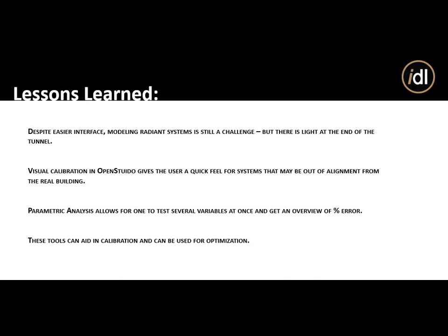And so what we've done before is actually take our EnergyPlus script, find all of our branches, and just eliminate our HVAC, import that into OpenStudio, and then rebuild it there so it's kind of OpenStudio friendly, if you will. So a lot of work.